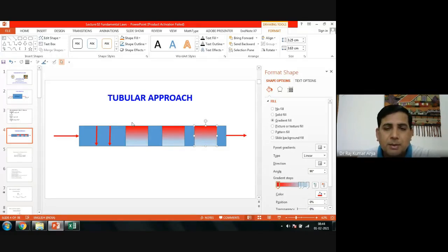But what will happen in this case is that whatever is inside this could be treated as one tank. Inside this there is no variation, but however if you reach this particular segment here, there is variation. So you can take this volume as small as possible to capture the entire behavior along this length. Your parameters, which could be your concentration, temperature, or density, may vary along the length. This is your length coordinate here.